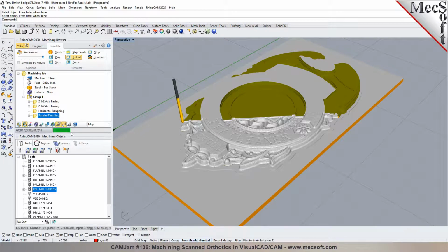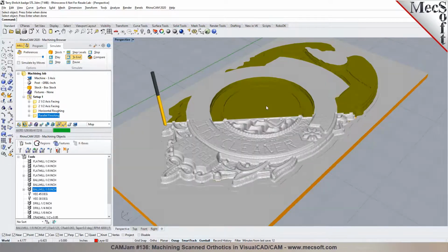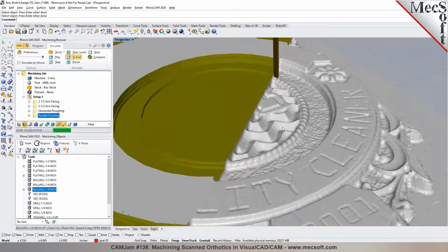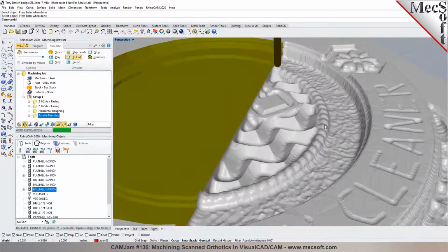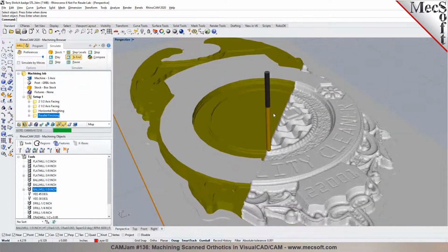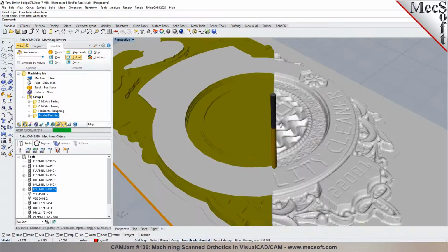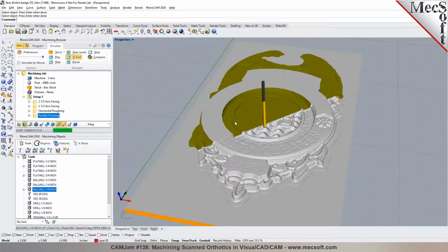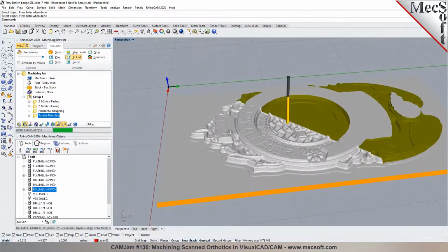It's running through the simulation right in here. I've chosen to go to N because there's so many toolpath motions in here, I can speed things up. I've set my simulation accuracy to run it really fine, so you can see all the details that show up as you're simulating it. If I set the simulation accuracy to standard or pick one of the other simulation models, it's going to go much faster. And anytime, like I said, you pause and then pick simulate to N, it's running through the toolpath simulation, cut material simulation.